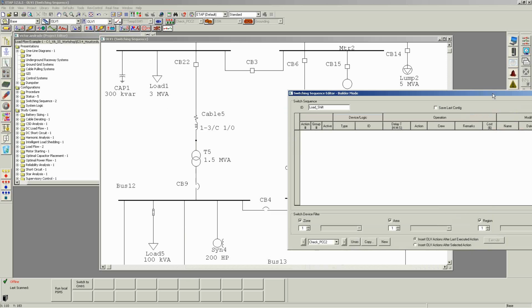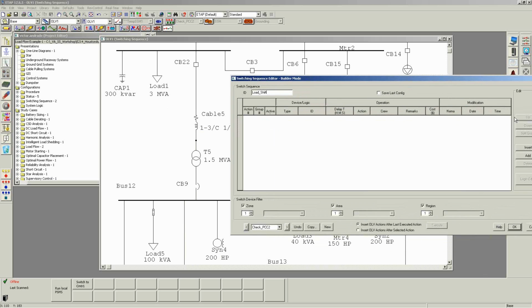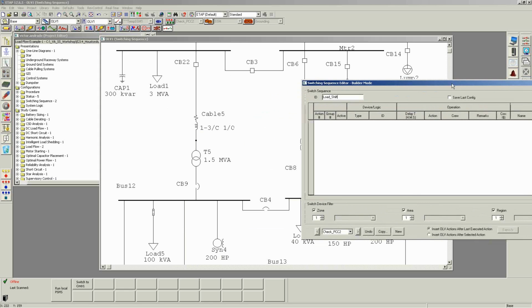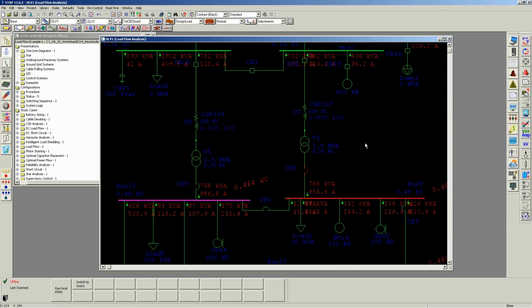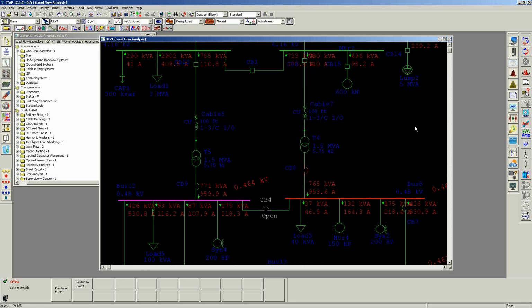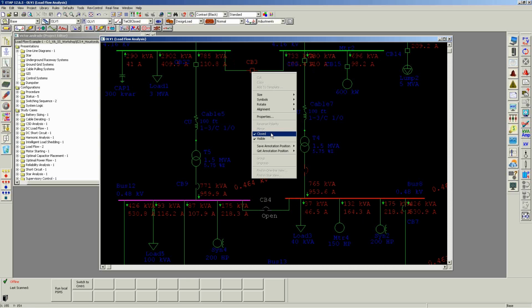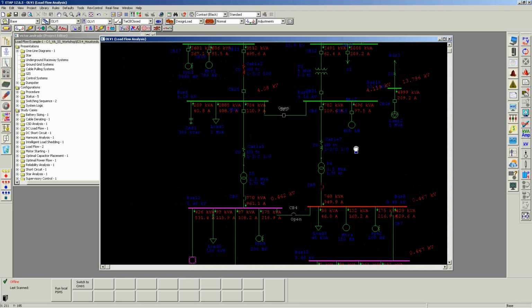Okay, and the first thing that we're going to do for performing load shift is we're going to close a tie. So we're going to close CB4. Give me 1 second. So what happens is, based on the existing condition, the tie is in fact closed. So I need to open it before. Okay, gotta open this.